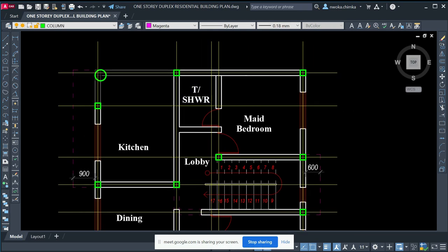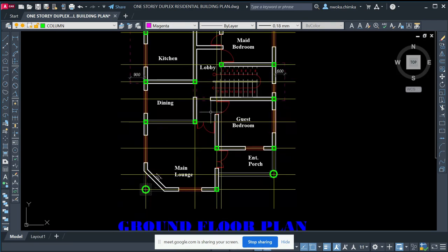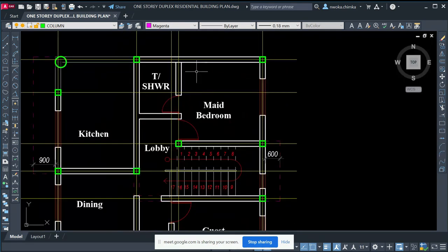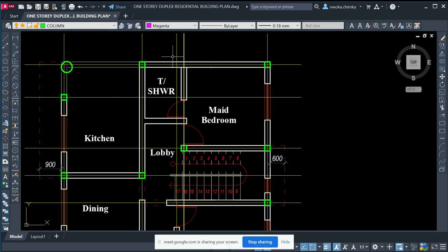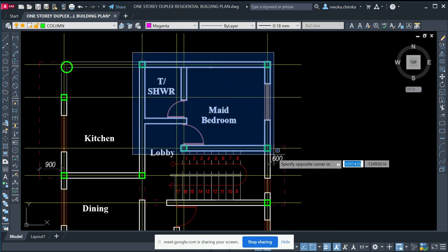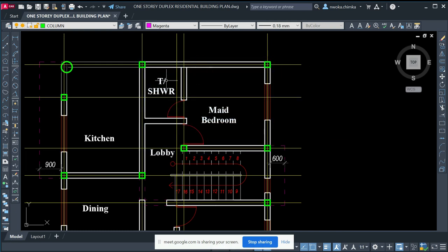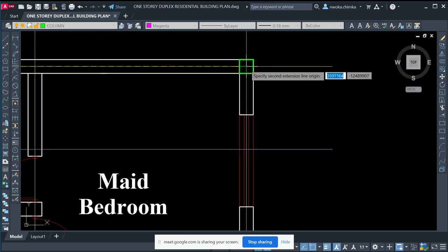Okay, so the same thing, I will now use the same principle to panel all my structure, to panel all these members. So I also check for this again here. We have a toilet here, and we have a maid bedroom here. So I'll check if this panel here can suit in, or if it is less than 30 meter square area. If it is less than that, I'll just take off all these toilet walls.